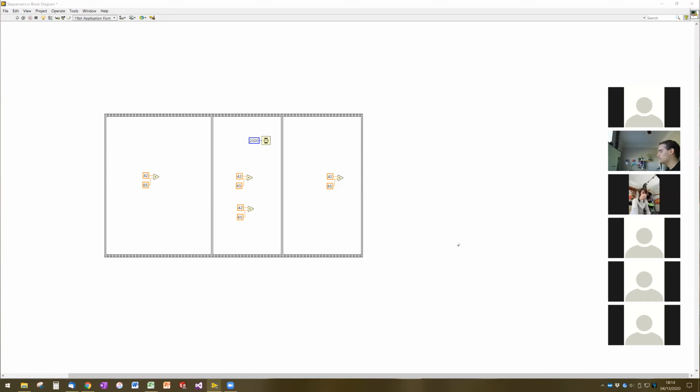And because we want to make sure everything else is synchronized, we put all of our state controllers that are making all of the decisions for the robot in the same control loop, which has advantages. But the disadvantage is that if you then do a wait, you're going to block the driver from inputting any new drive commands while we're waiting for the elevator to retract or for any other wait that's occurring in the sequencer.